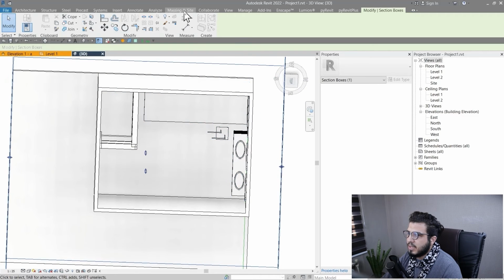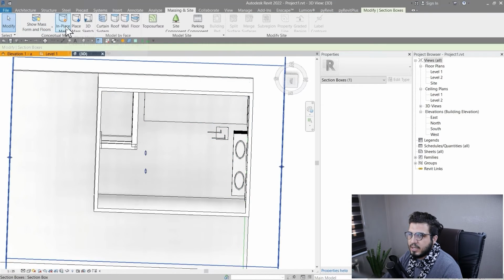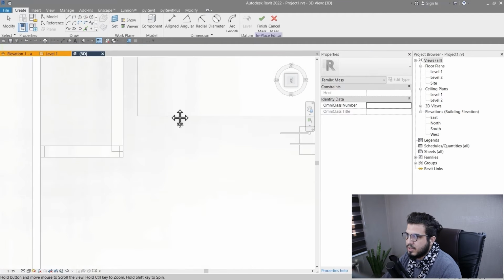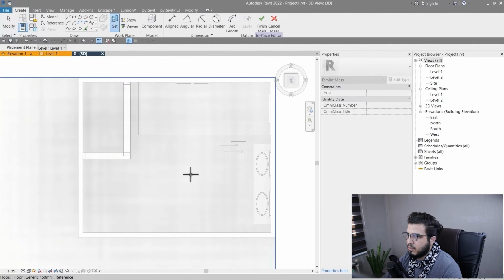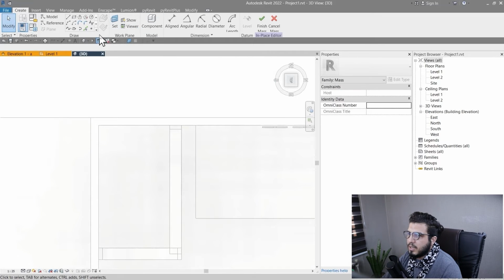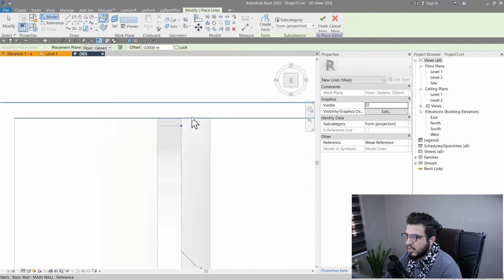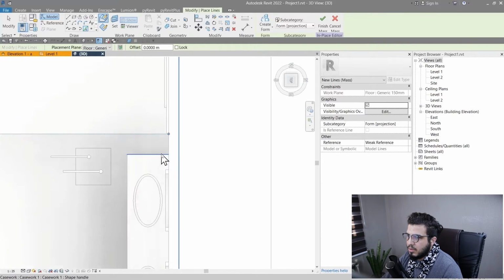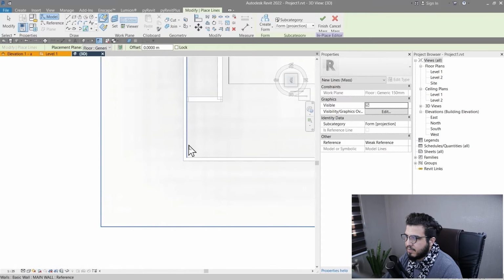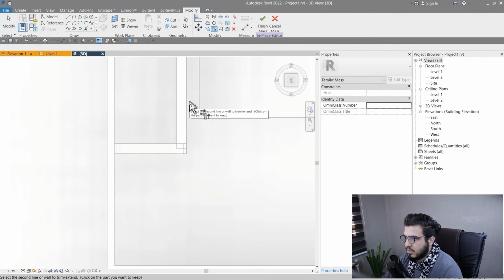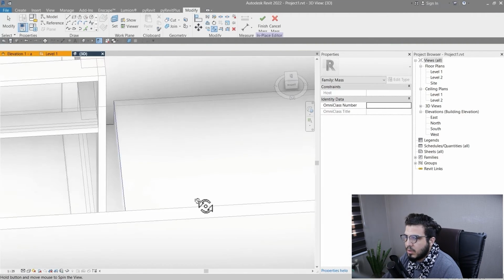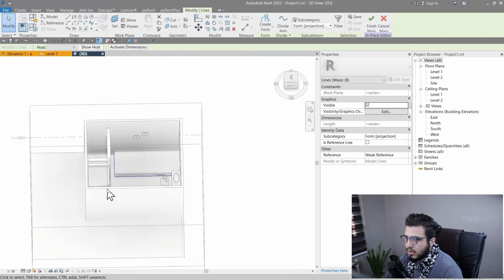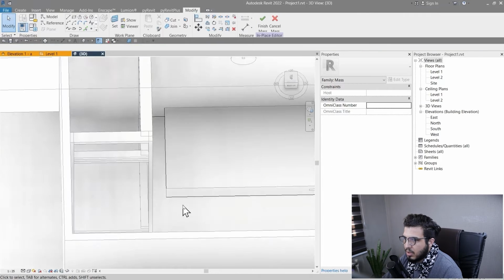Let's go to the massing side and let's activate the show mass part, and let's create two surfaces for these parts that we need. First of all, let's set our work plane on this part and let's pick all of the lines that we need to create our mass surface. They are not in a work plane, so let me delete all of them. Are they in a work plane? No, they are not in a work plane.